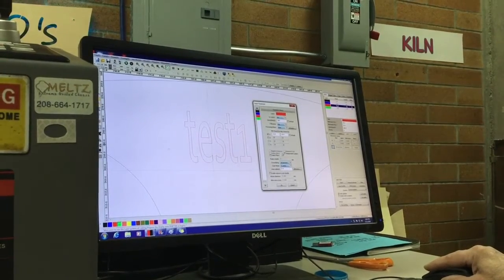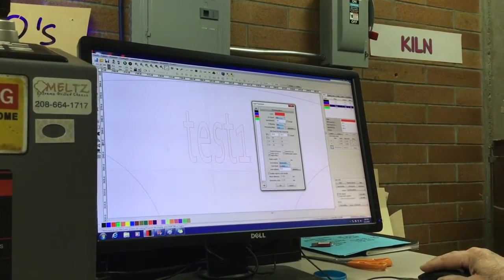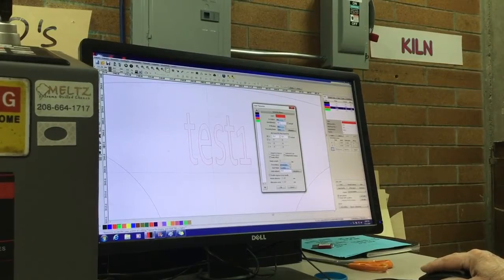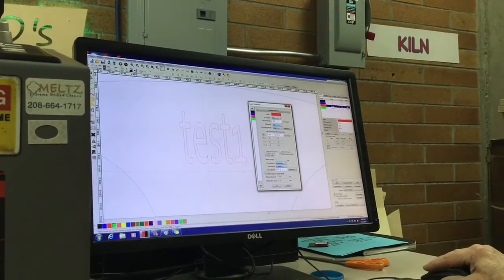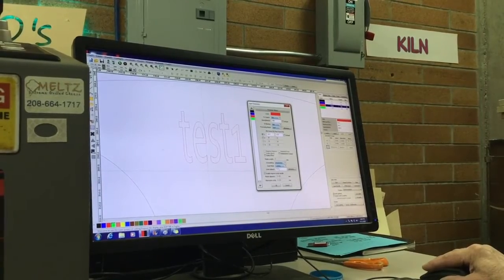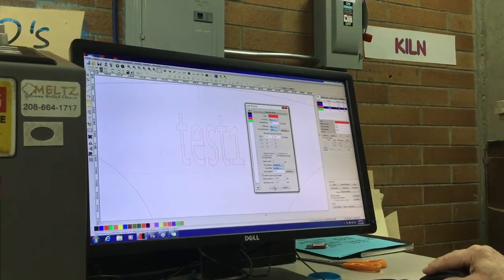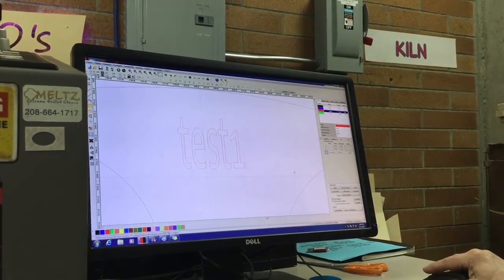So we're happy with these. This is our typical setting for a scan: 200 millimeters per second, something like 15%, 0.2 of a millimeter for the interval, and say OK.